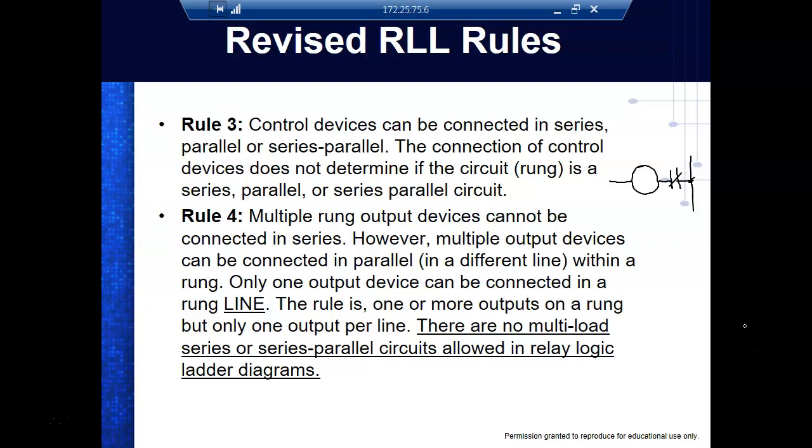So what happens is the motor comes down, and we would have the contacts out here in another circuit. This would be 3-phase. And then we'd come down through here and we put what we call an overload sensor that senses when the motor draws a lot of current over time.